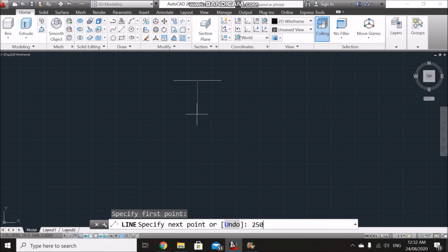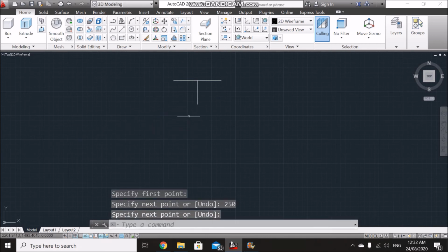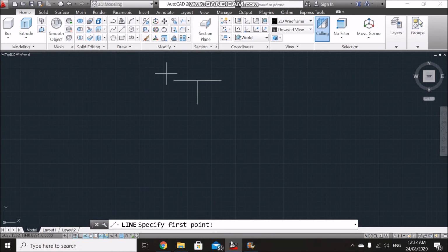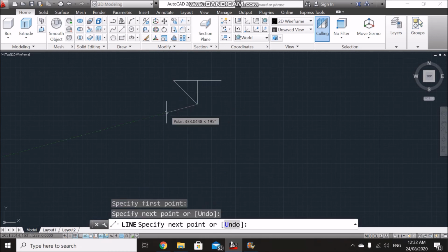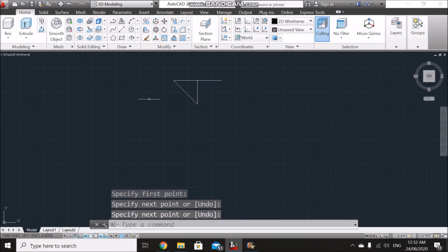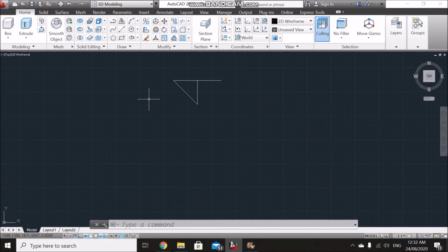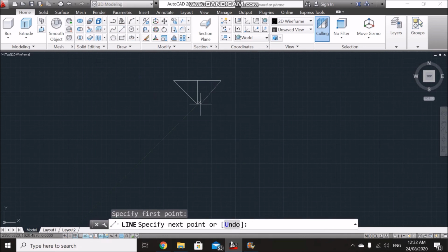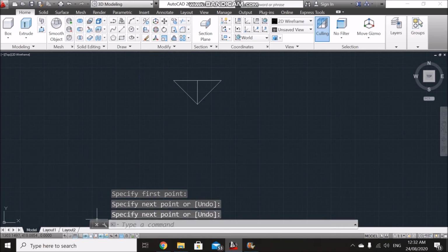object snap is in this particular software, because it lets you detect the end line, the midpoint of a certain object that would be really hard to find when you're trying to look for it manually. Actually, it's quite impossible to get the endpoint doing it manually. So this is very important when it comes to 3D modeling and 3D drawing. So always check on that object snap.